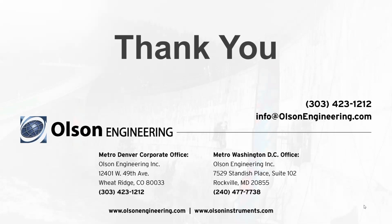So next question is, what do you recommend for concrete defect detection where there is an asphalt overlay, and does having the asphalt overlay make it easier or harder? You definitely want to take a look, if you can, at the YouTube for Olson Engineering, because in the bridge deck portion of that, we've done research on both asphalt pavements and asphalt overlaid bridge decks using impact echo and surface waves. And the surface wave technique is able to discriminate between a debonded asphalt based on wavelength and a drop in velocity at that depth.